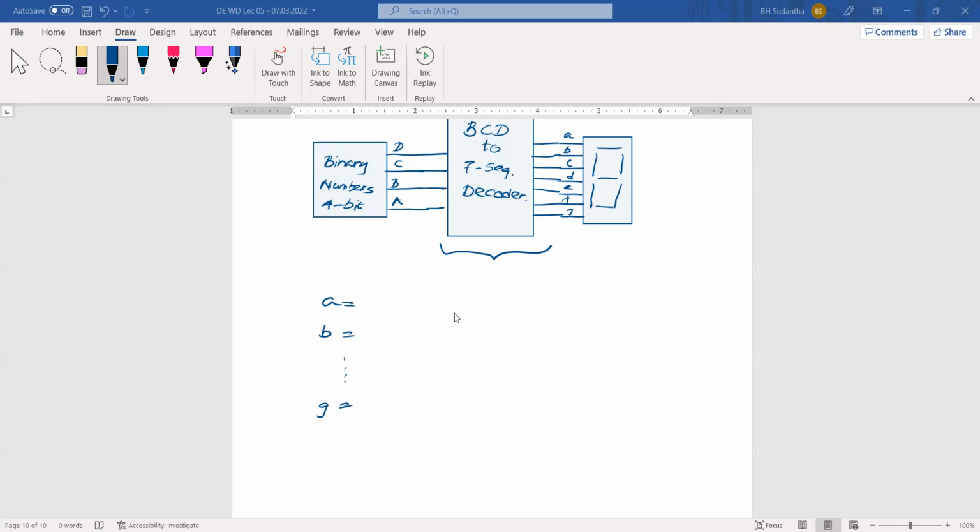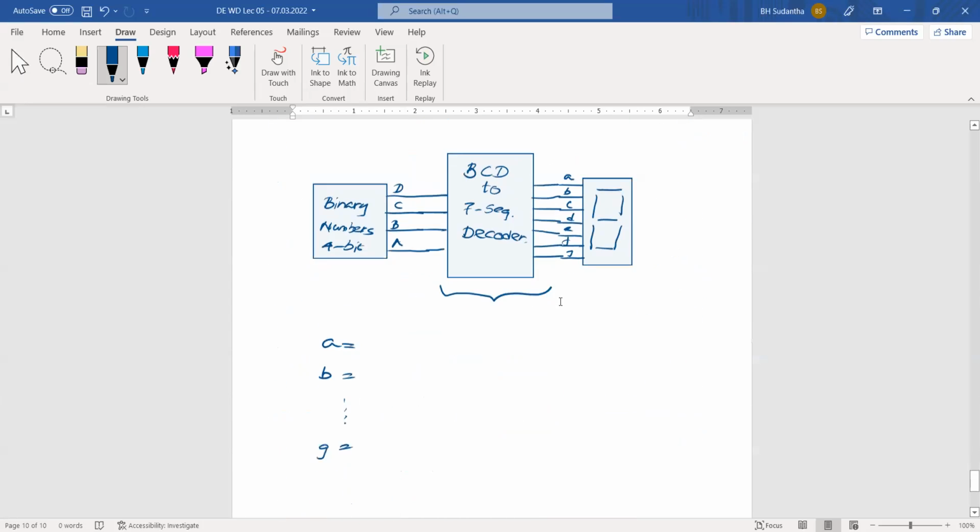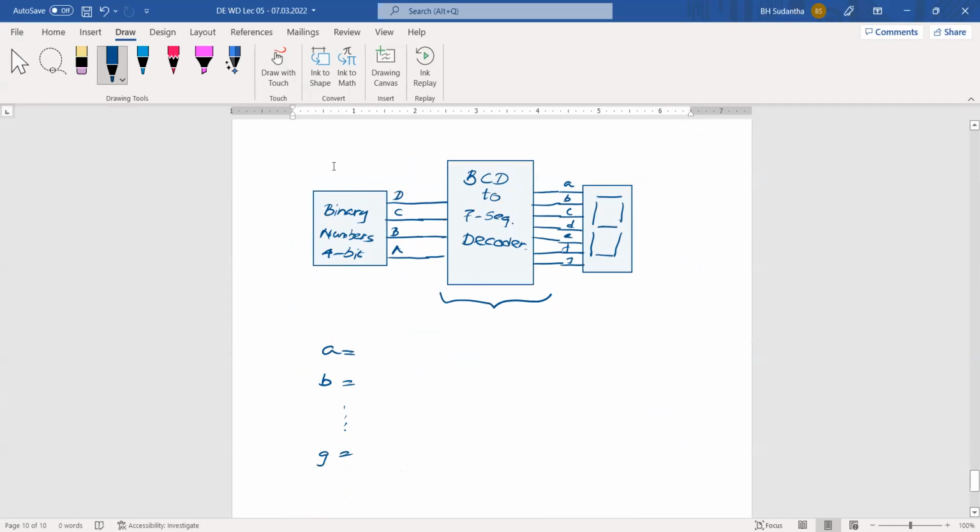When you use standalone gate ICs for the development, it may be that type of circuit. But in this case, we are not going to design that, but you should know how to design. Then for the BCD to 7 segment decoder, you can have the binary bit pattern generator circuits here. And if you want to show your number on a display, we can use the BCD to 7 segment decoder in between these two. Then finally, you can show your number on the 7 segment display.